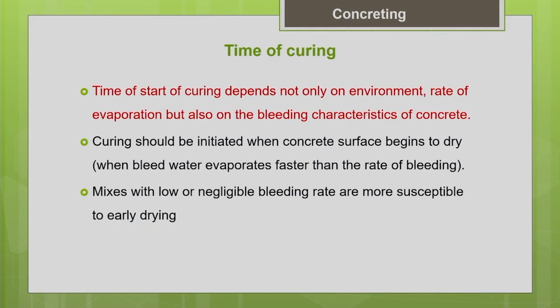Generally we cannot generalize when the curing has to be started for a concrete. What should be the right time of curing varies from concrete to concrete, and from environment to environment where the concrete is being placed. In aggressive environment conditions where the rate of evaporation is very high due to high wind velocity or high temperature, we have to start the curing as early as possible. And it also depends upon the concrete composition.